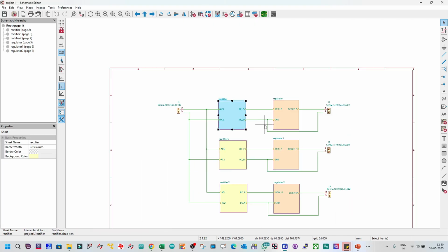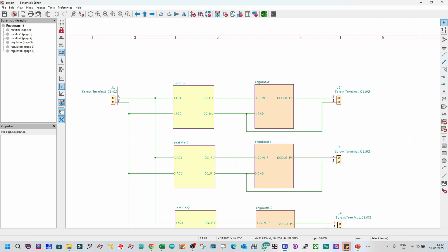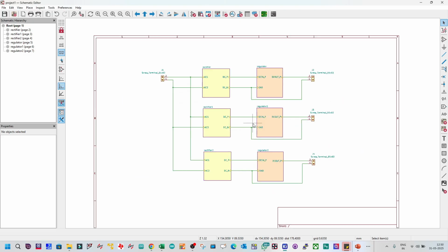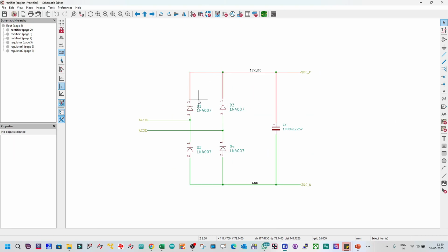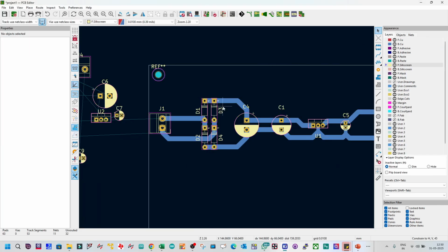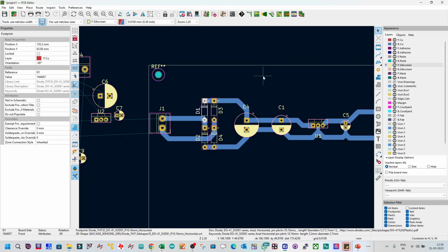See, this routing we have completed: this connector, rectifier, regulator, and connector 2, output connector. This routing we have completed. We don't want to reroute this. We just want to ditto apply the same routing to all this. So you just go to this block. We'll select one component, not here, in the schematic. Sorry, in the layout. You go to D1, hit on replicate layout.